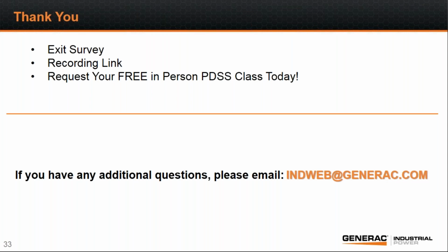What is generally the safest voltage dip to prevent contactors from chattering? For NEMA contactors, anything under 35%. I would normally design with a little extra headroom in there, probably in the 25 to 30% range. When you're looking at it holistically, sometimes the best solution is just to look at the biggest motor and say, let's take the biggest motor out of the equation and either put a drive or a soft start that does voltage ramping, and let's fix the problem at the source instead of trying to kill it with generator size.